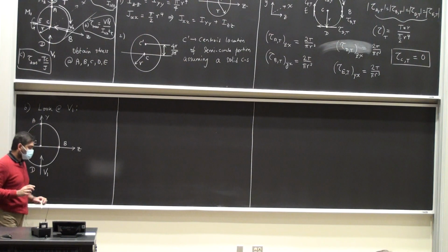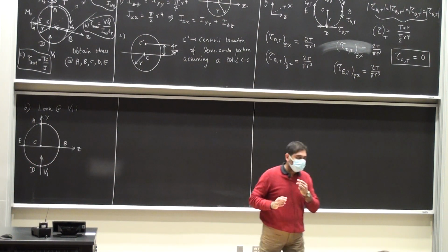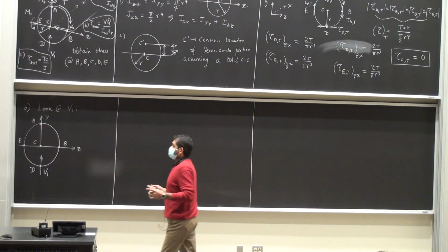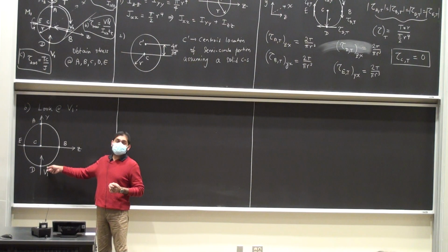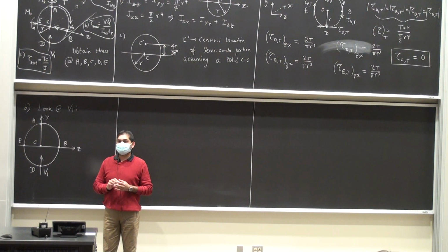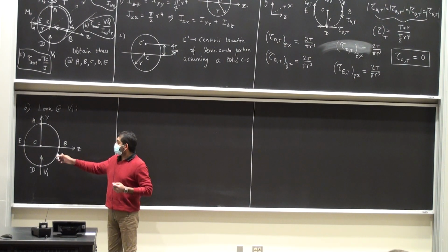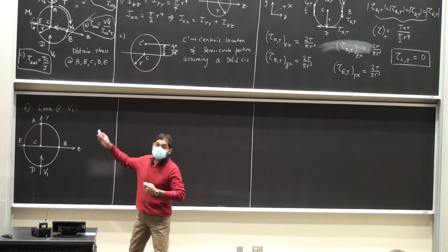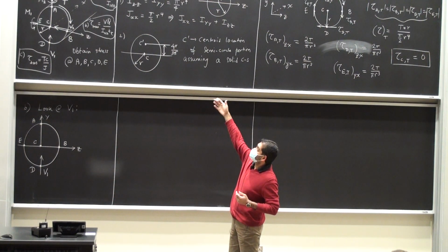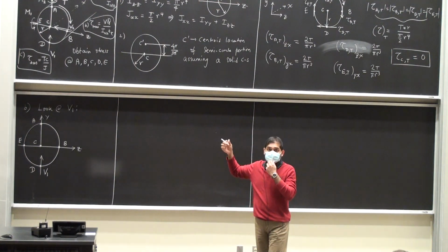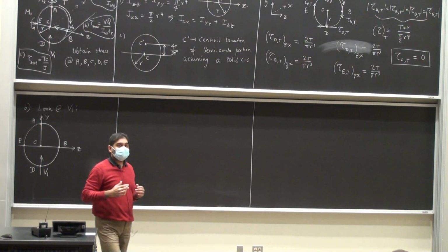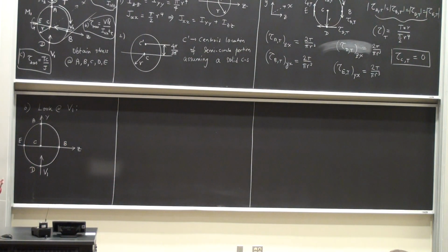My question to all of you, we decided something last time. First of all, if the shear force is V1, what is the direction of the neutral axis for the shear force? It will be perpendicular, fantastic. It will be perpendicular to the shear force. So something to keep in mind, if I have a shear force, the axis that is the neutral axis for this shear force is the z-axis, which means if I'm looking at that other shear force V2, the y-axis is actually the neutral axis. For this cross section, it makes not much of a difference because the values will end up being the same in some sense. But if I have an odd-shaped body, which we are going to look at, like a T cross section or an L section or a C section, it makes a hell of a difference as to what is my neutral axis.